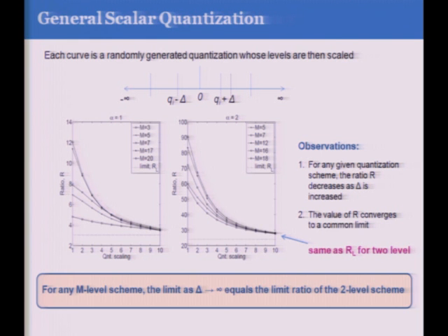I guess that's the thing that I'm a little lost in. It looks like you're throwing away the constant. Why not just spread them out uniformly, so as to preserve zero? I just don't understand how it preserves the binning. Okay, so you mean why is it not uniform quantization? Well, in this particular case, you're making the center bin really big and effectively shrinking the others, where instead maybe you could spread them out evenly and have more and more bins. Right, but how do you preserve the probability? Because you're essentially shrinking the probability that any of the other levels get touched.